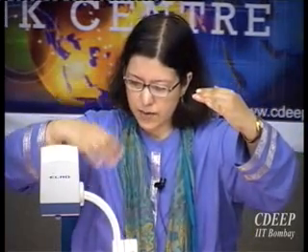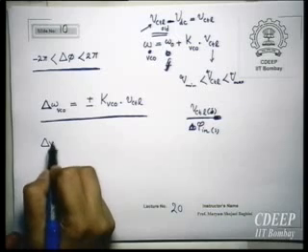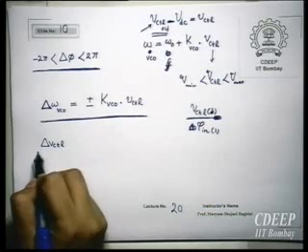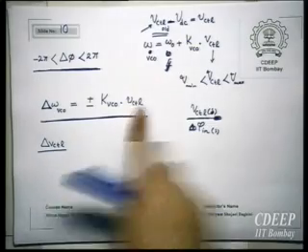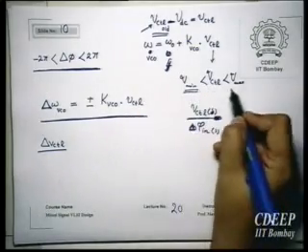When it goes to this new frequency, VCTL will go from VCTL1 to VCTL2. But what is this maximum difference? This depends on how charge pump changes this. So I consider this delta VCTL due to change in my input frequency can maximum go into this range, Vmin and Vmax.